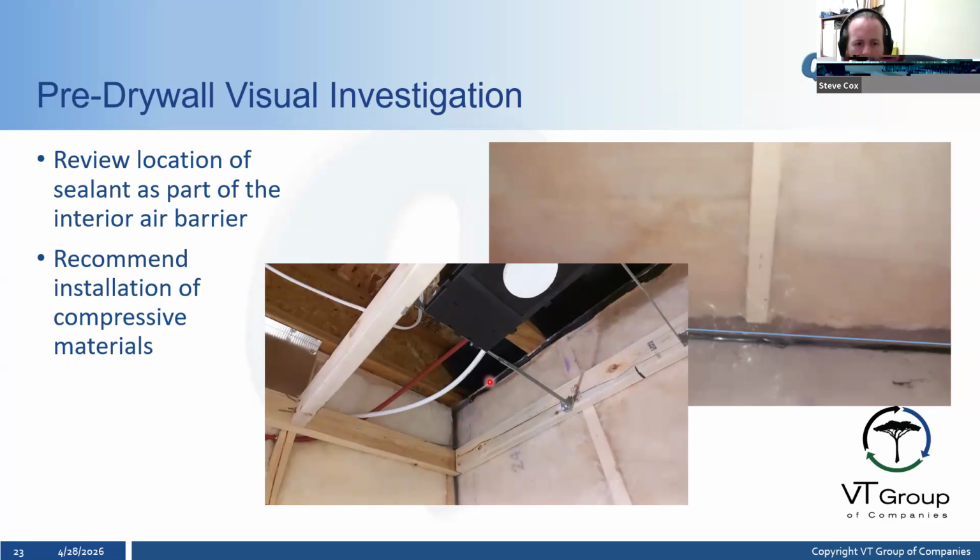It won't seal the poly to the framing anymore. So we need to have a structural compression in place around this detail here to make sure that that air barrier stays in place where we want it to stay for the duration of the building.